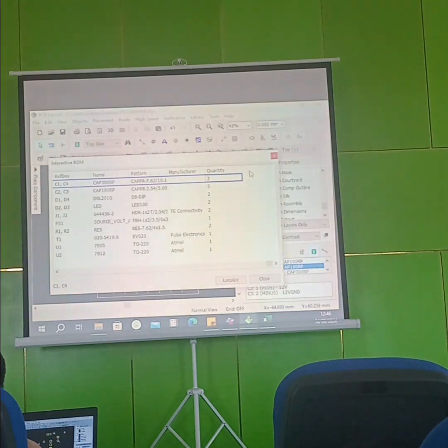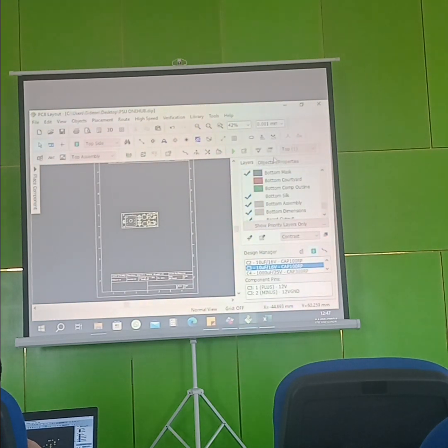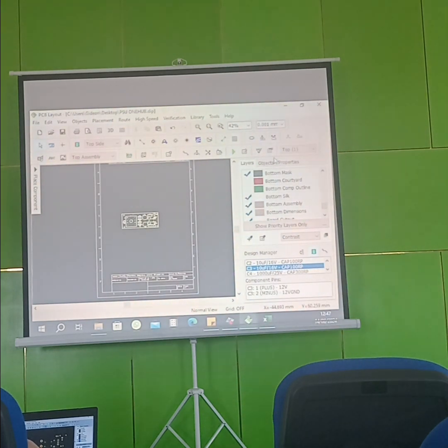So now I want you to export your Gerber file, your drill file, pick and place file, STEP file, and do your BOM. Do it and put it in one folder. Forget about what you are doing now. Maybe you've not finished your design. No, you can do it without.